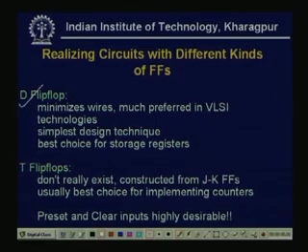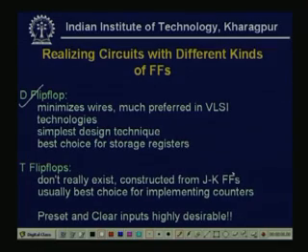Normally, T flip flops do not really exist as such. The toggle type of flip flops are constructed from JK flip flops, because we have seen that the JK flip flop mainly toggles, and it is usually the best choice for implementing counters. Normally, for whatever the type, preset and clear inputs are highly desirable. So, whatever flip flop implementation or type we use, we prefer to have one clear line and one reset line.